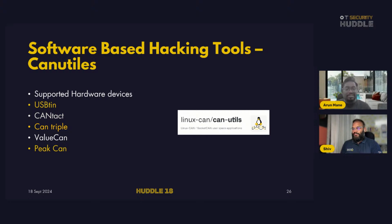can-utils is another library, which is again open source. If you install it on Linux, again the Linux operating system is open source. You have to compile these things and you can start working with can-utils, and it does a ton of things. So what hardware tools does can-utils support? On the left side you can see USB-tin, CANtact, CANtrip, ValueCAN, PickCAN. These are the hardware devices can-utils works with.